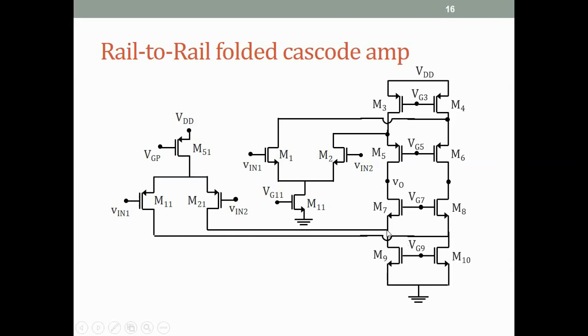That differential current is fed into this circuit, and both of these currents are added at this node by this circuit. So this full circuit achieves the addition of the differential currents due to the NMOS and PMOS differential pair by this cascode configuration.